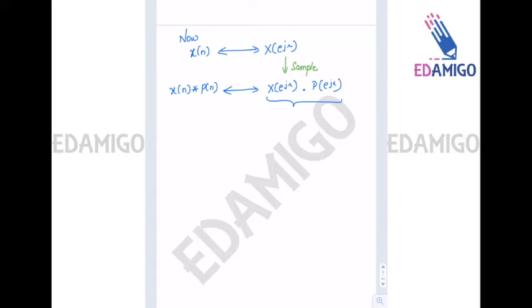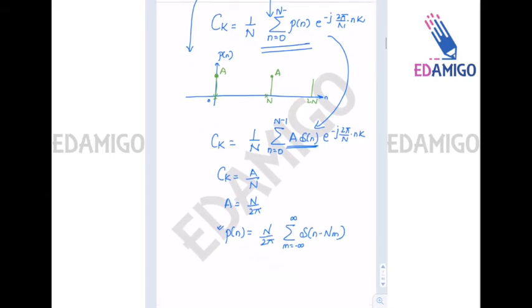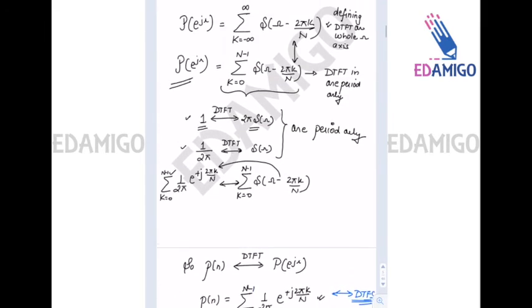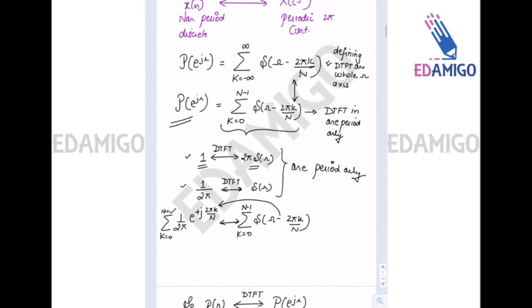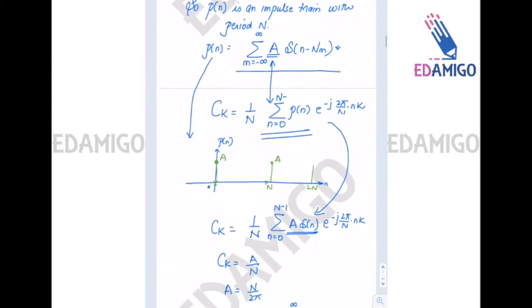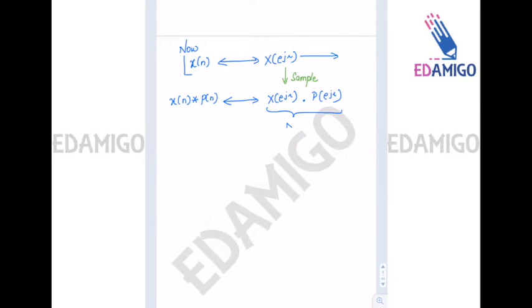Okay, so this will give me, so what is the equation number? We've used somewhere, no? Equation number 1 was there. Okay, so 1 is only there. So this is equation number 2, this is equation number 3. Equation number 2 is the simple DTFT. In equation number 3 we have sampled the DTFT, and this is now called the N-point DFT.